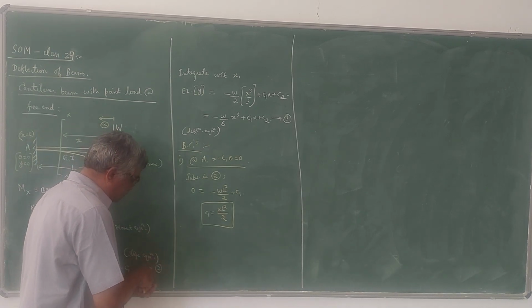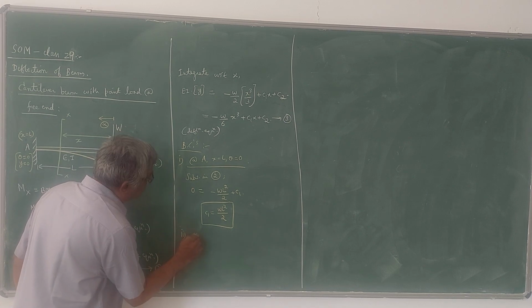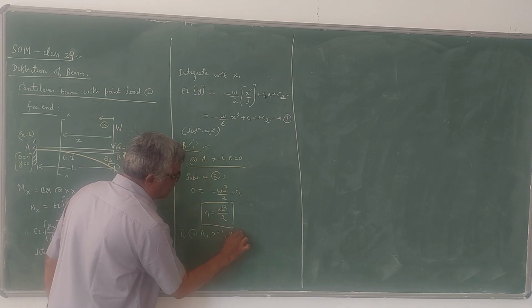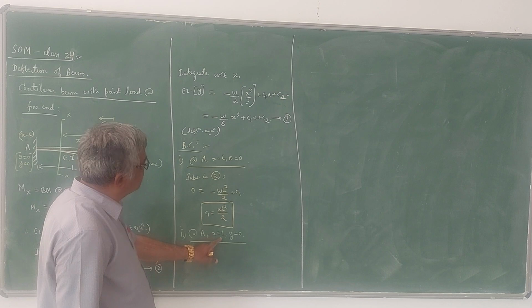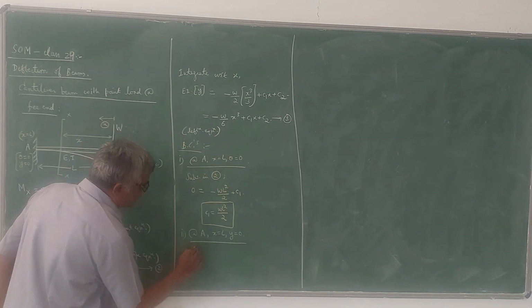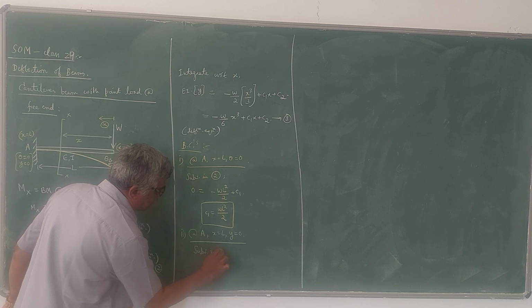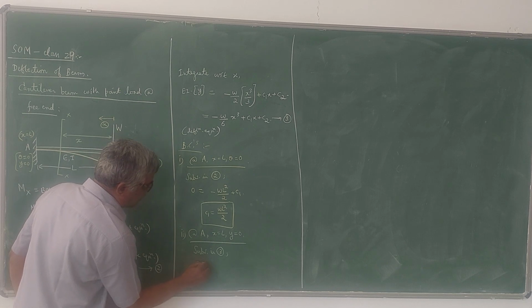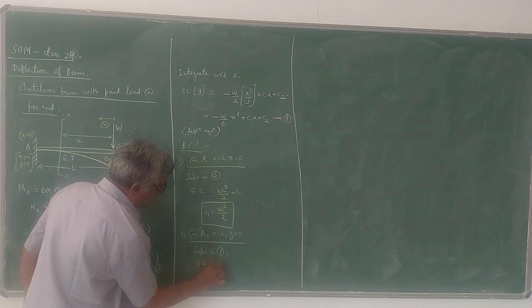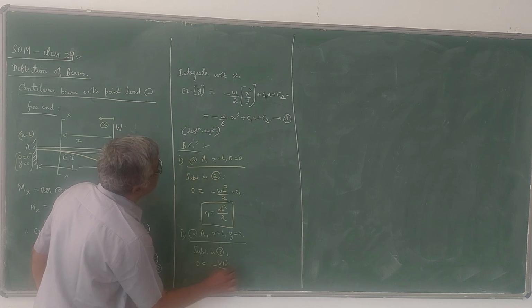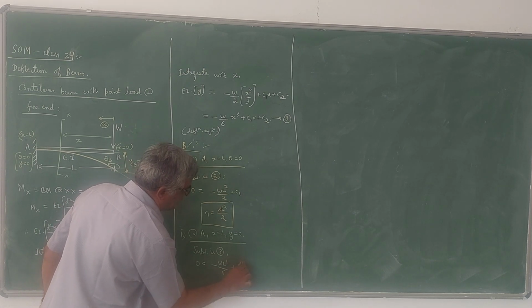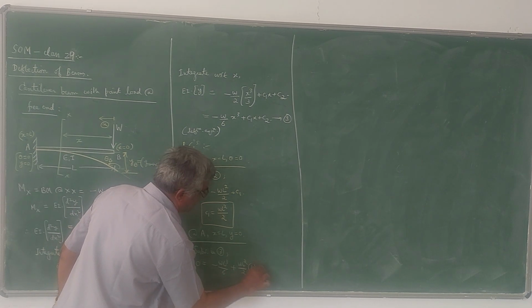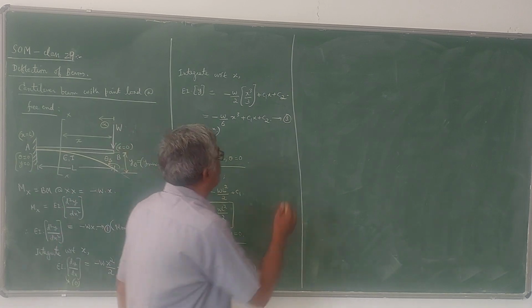Second constant of integration is obtained by using the second boundary condition. Second boundary condition is at A, at the fixed end. Once again, x is equal to L. Deflection is also 0, y is also 0. Since deflection is involved, we have to substitute in the third equation. Substituting in 3, LHS becomes once again 0, y is 0, is equal to, x is L here, minus W L cube by 6 plus C1, which is W L square by 2, into x, which is once again L, plus C2. So from this we can get the value of C2.